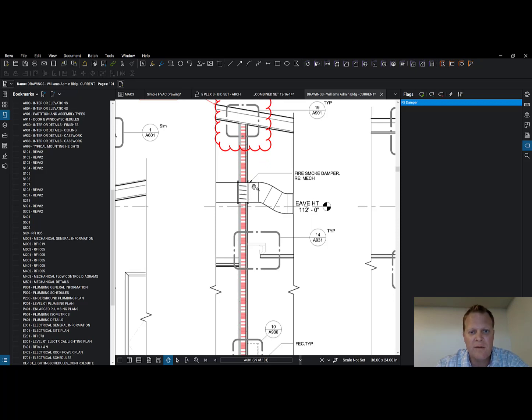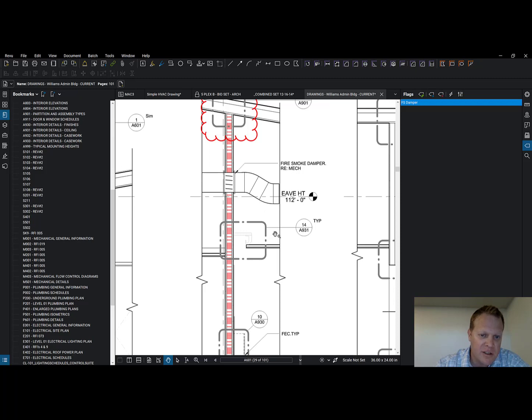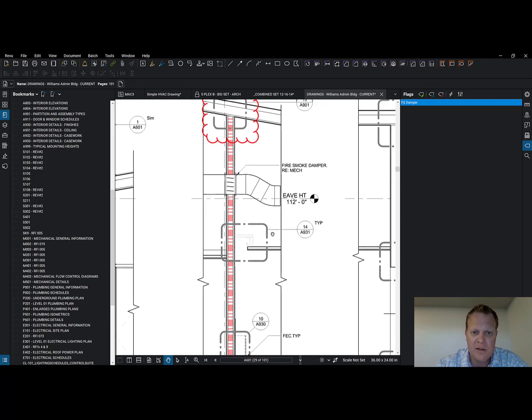If you have ductwork going through a fire rated wall, a lot of times they have something called a fire smoke damper, which will close and not allow air to continue to pass through this fire rated assembly, assuming it might be receiving smoke or something in the duct, right? Or you don't want to continue to supply fresh oxygen to this space over here through the ductwork. If it was on fire, we want it to run out of oxygen.